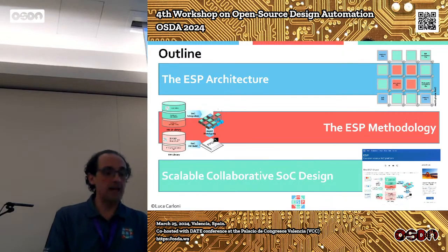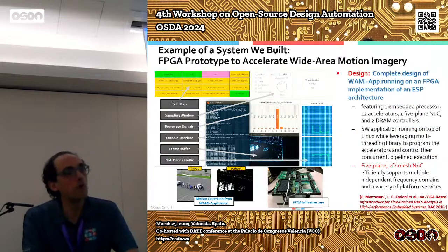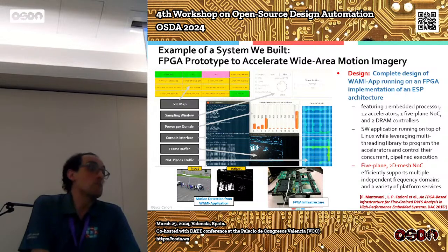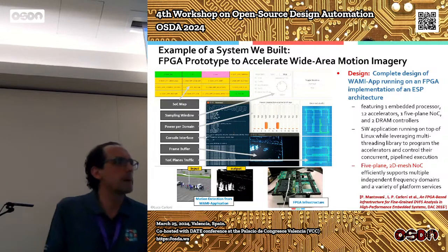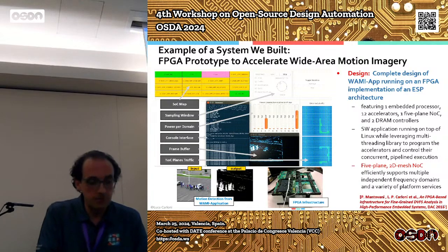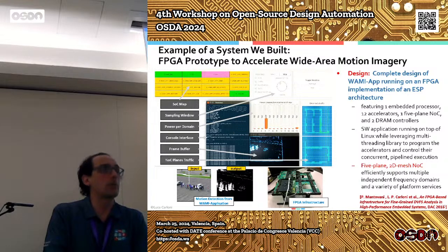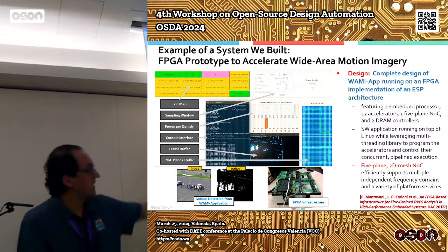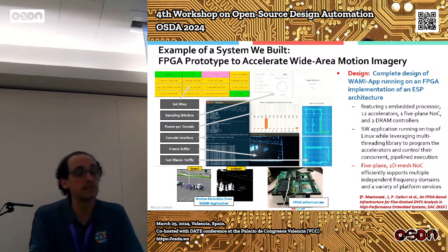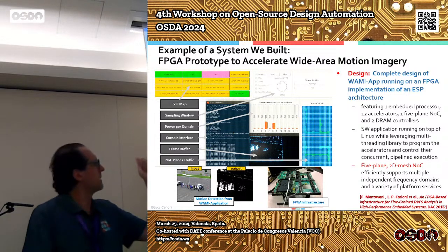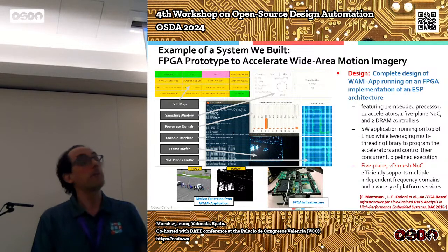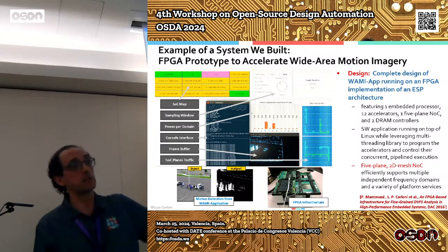Now, in the remaining time, very quickly. For many years, we focused on developing SoCs on FPGA, essentially emulating the SoC on FPGA, and we developed quite complex SoCs. This was presented at DAC almost 10 years ago. This is for a computer vision application, and what you see here is a live demo from the time where the heat map on the right-hand side tells you where the traffic is going, while you have, if I remember, 16 accelerators. There is one processor, a Leon 3 processor, an IO tile. In this particular picture, there are two memory tiles at the two opposite corners.